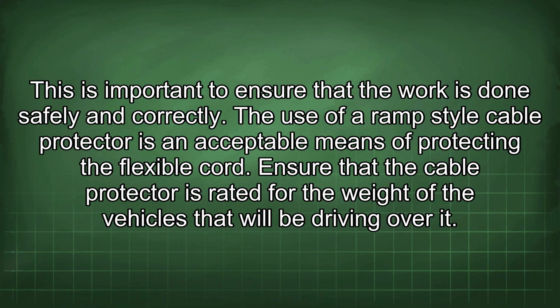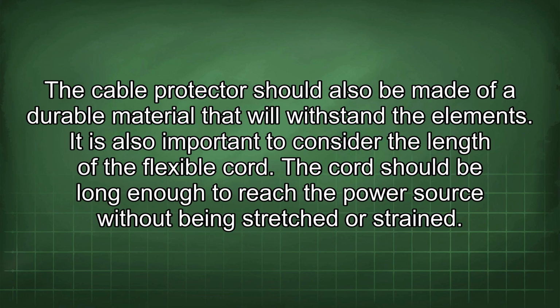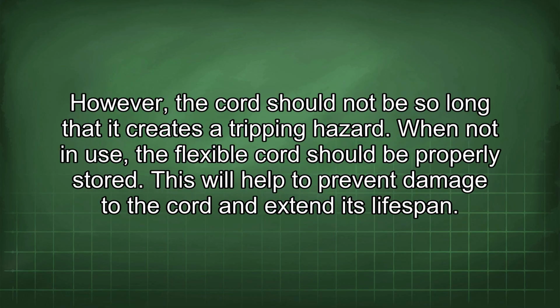The use of a ram-style cable protector is an acceptable means of protecting the flexible cord. Ensure that the cable protector is rated for the weight of the vehicles that will be driving over it. The cable protector should also be made of a durable material that will withstand the elements. It is also important to consider the length of the flexible cord. The cord should be long enough to reach the power source without being stretched or strained. However, the cord should not be so long that it creates a tripping hazard.